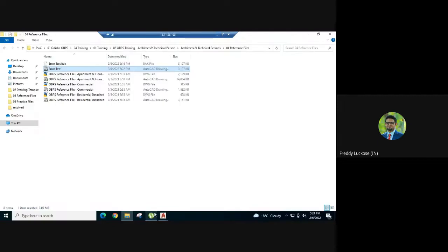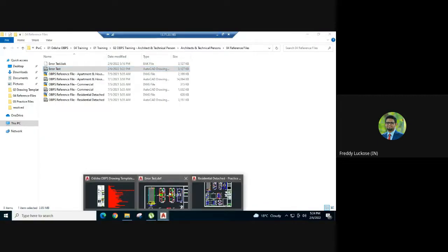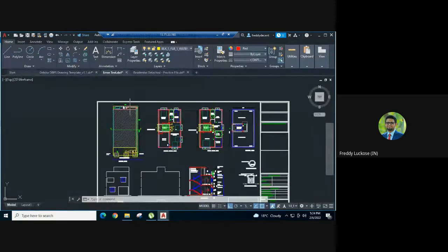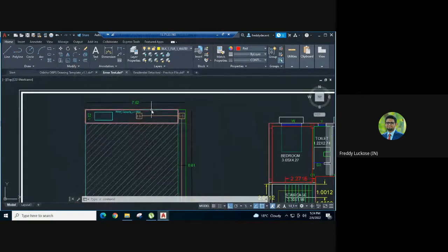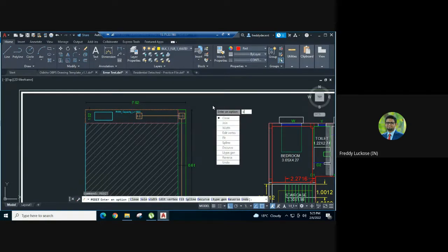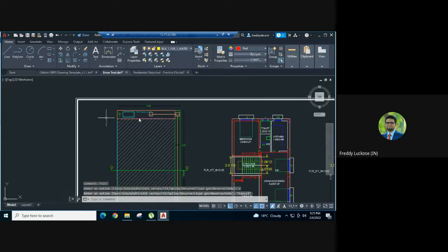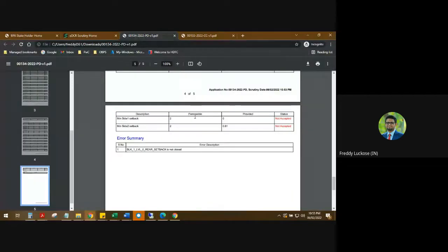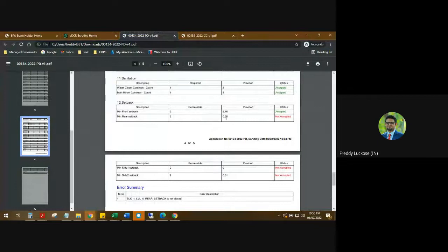have to do is go back to the drawing, select the polygon that is not closed, and then use the command pedit to close that polygon. So I'll use pedit, then enter, then C enter for close. So this has closed the rear side polygon. Let's see if there's any other issues happening inside the drawing.